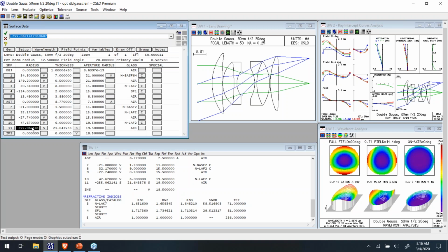And if you don't do that, anybody who's forgotten to do that in a lens, lenses tend to like less and less power, so longer and longer focal length. So you usually put constraints on those things. And there's a lot of different ways to do those constraints. You can do them in your optimizations inside of the optimizer, the operands, or you can constrain them in the program like I've done in this case. So lots of different ways to do that. A lot of flexibility there.